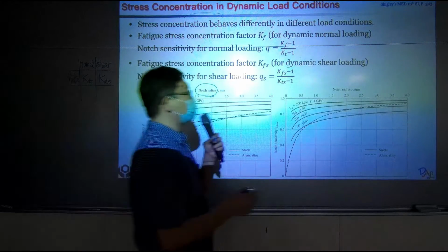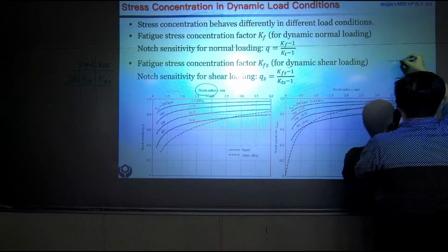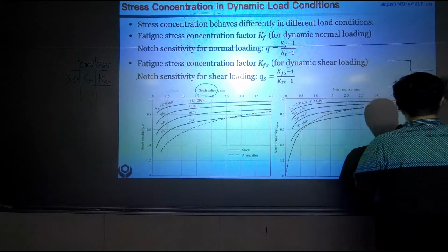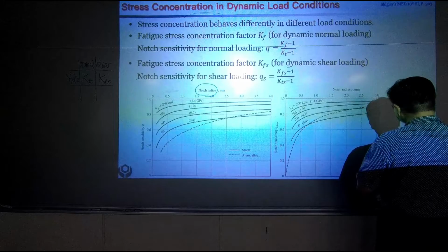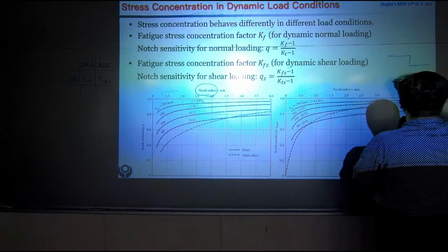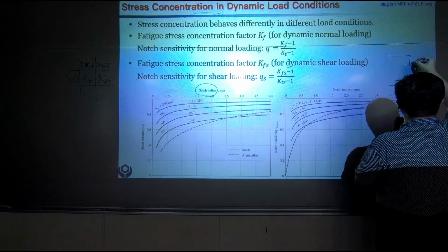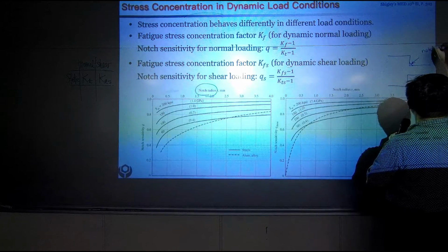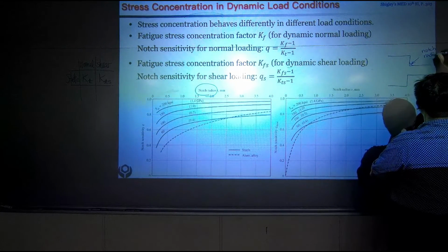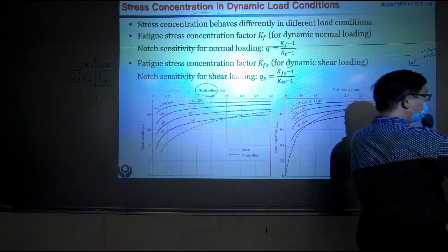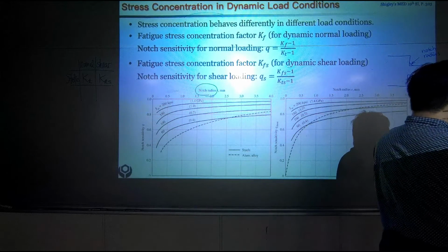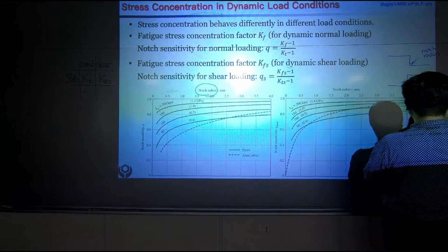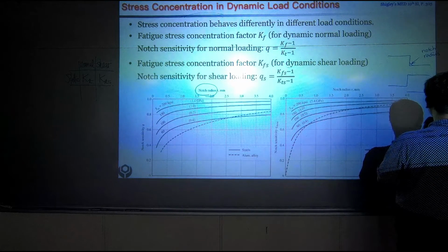So what's notch radius? For example, if you have a geometry like what we have drawn, you can consider this part as a notch, and you can say this is a notch radius. Basically, the location where you have geometrical change and then the radius of it. Another case would be like this.